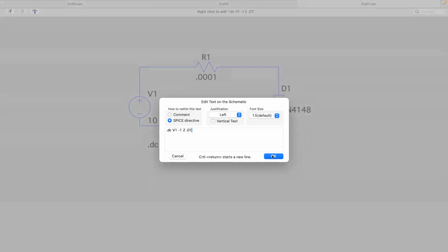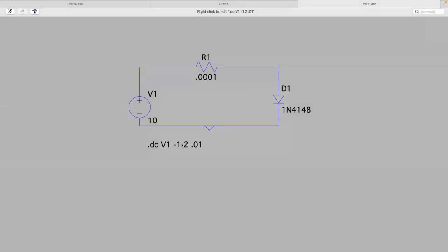Okay. Yeah, so that's pretty much all you need to know in order to get to a basic graph. I'm realizing now I never really described diodes. The graph I just showed you is the textbook graph that everyone's going to give you for telling how a diode reacts to forward current. So when current is passing through this way, you can think of it as an arrow. The arrow means that you're going to be able to push current through it in this direction. If you try to push current through in this direction, it's got this line that indicates that it's a block. You won't be able to push current that way.